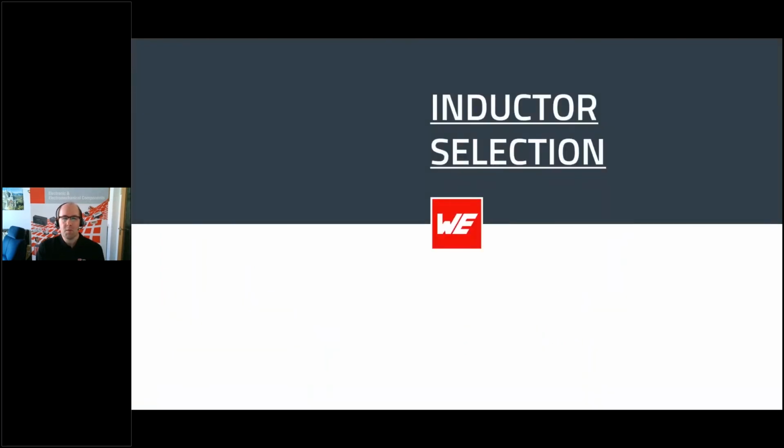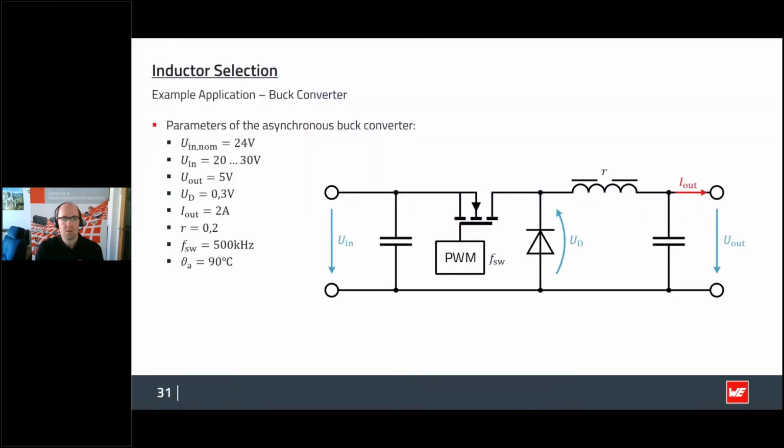The last chapter regards the inductor selection. Before I show the live demonstration using the REDEXPERT tool, I will show you the example which I have selected. It's an asynchronous buck converter with a nominal input voltage of 24 volts, an output voltage of 5 volts, a diode voltage drop of 0.3 volts, and an output current of 2 amps.